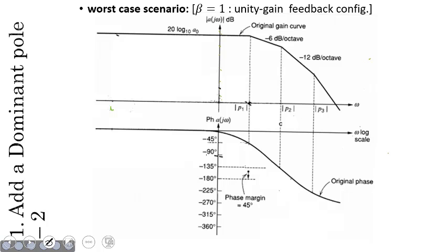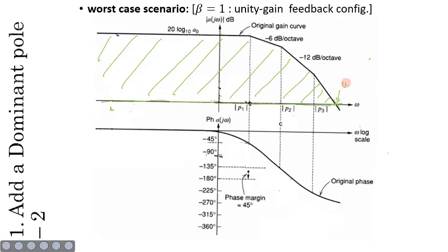So when we plot our closed loop magnitude plot, this plot would appear at 0 dB, and this entire open loop transfer function that we had would be exposed to the loop gain magnitude plot. And where exactly would be our omega gx, or gain crossover frequency? It is the intersect between the open loop and the closed loop, right? So it would be at this particular frequency that we have omega equals omega gx.